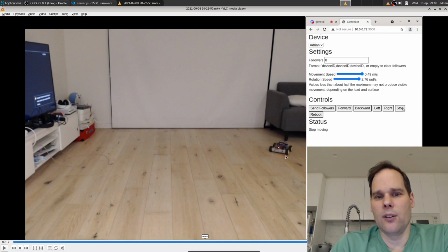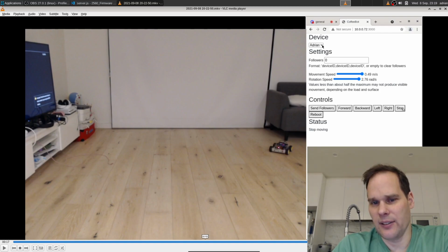In this case, there is another client running on the robot itself, which is listening to the same message that it receives, checks that it's an appropriate movement command and it's for its device rather than for the other devices, which could be anywhere in the world, and then converts that into a message to send through from the Raspberry Pi into the Mega using this USB cable that connects the serial ports.